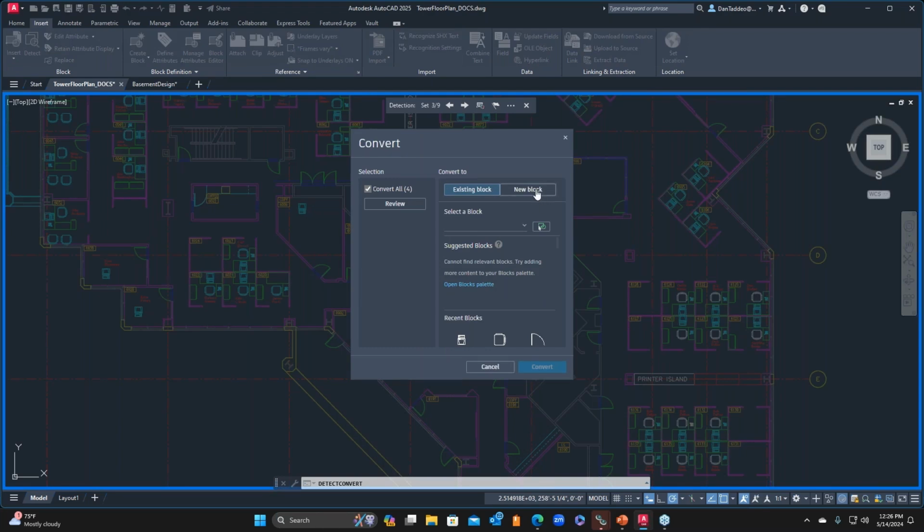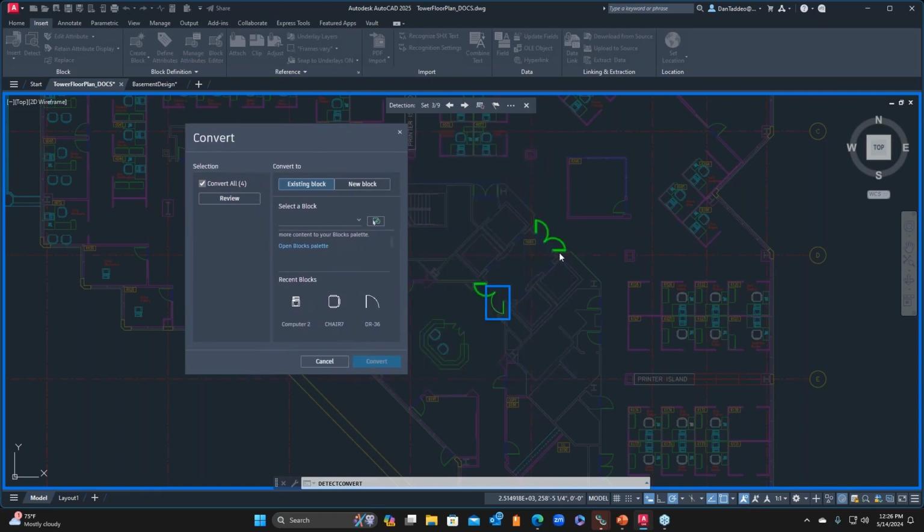And so at this point, I can choose another door, but you've got to be careful because the other door, let's take a look at this. You can see how the door swing is actually considerably wider. The 90-degree may not be the best choice, right? So maybe create a new block and give it a name. So I'll just call this, let's do door 2. Anytime you have something that already exists, you'll get feedback instantly.